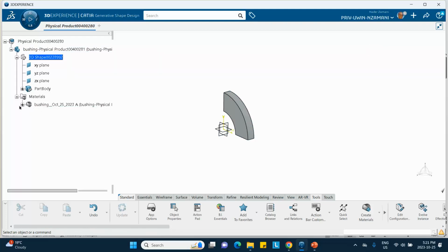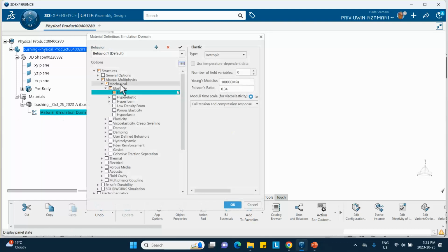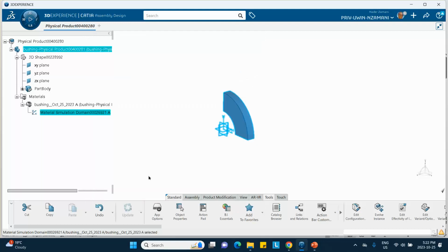And let's go and input the values. There's only Young's modulus and Poisson ratio. That's all we want. Obviously, the problem can be done. Okay, that's fine. I already have something by that name. So 100,000 MPa and Poisson ratio 0.34. Say okay. Good. We are done here.